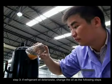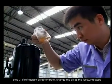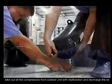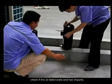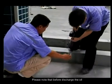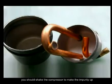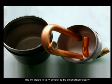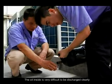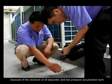Step 3. If the refrigerant oil has deteriorated, change the oil as in the following steps. Take out all the malfunctioning compressors from the outdoor unit and discharge the oil. Check if the deteriorated oil has impurity. Please note that before discharging the oil, you should shake the compressor to stir up the impurity. For the oil separator and low pressure accumulator tank, the oil inside is very difficult to discharge completely because of their structure.